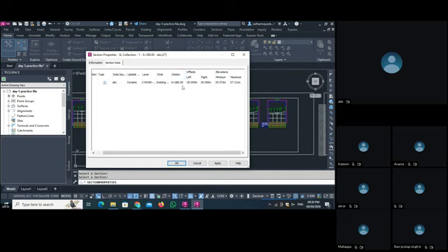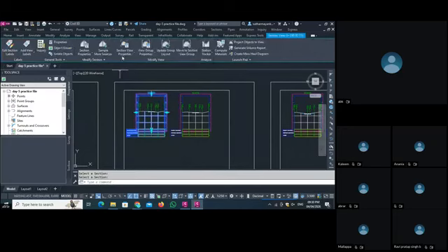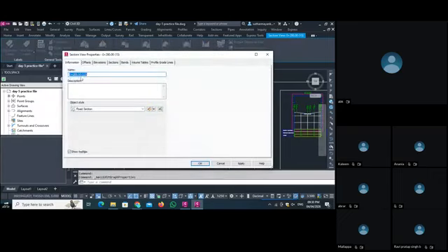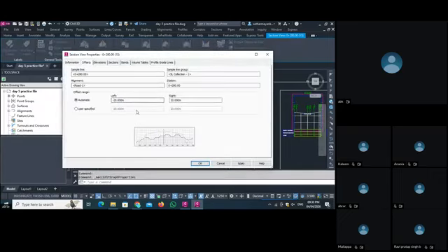The change is this offset, which offset we take, what is the minimum and maximum elevation here. Okay, the ground is selected, type is selected. So all the description you can check from here. If you go in a section view properties, if you click it here, you can see the particular changes. You can modify that section from here also.